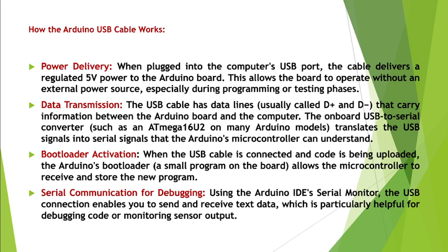Bootloader activation. When the USB cable is connected and code is being uploaded, the Arduino's bootloader, a small program on the board, allows the microcontroller to receive and store the new program. Serial communication for debugging. Using the Arduino IDE serial monitor, the USB connection enables you to send and receive text data, which is particularly helpful for debugging code or monitoring sensor output.